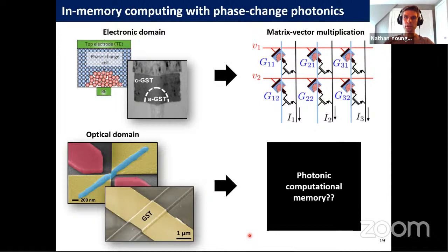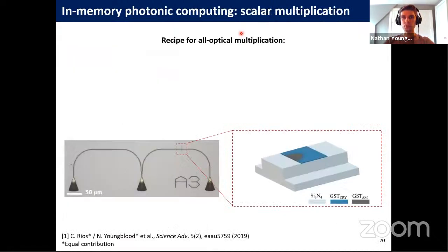And this idea is really inspired by recent work on analog in-memory computing architectures that use resistive memory elements to perform multiple matrix vector multiplications, or a single matrix vector multiplication in a single clock cycle. So we put input voltages and we change the conductances of these phase change memory cells, and we measure the currents, and we get an output vector from an input vector times a multiplication of this matrix. Now, doing the same thing in the optical domain could lead to a dramatic improvement in computational throughput. So how would we do that?